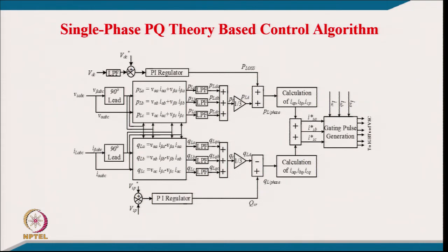All these 6 quantities consist of ripple and a DC component. The DC component corresponds to the fundamental active power and reactive power, which we get using the low pass filter. These can be different values, because you might have an unbalanced load. Similarly for quadrature, the reactive power DC component can also be different, as you might have load unbalancing across all 3 phases. So, summing all 3 and then dividing by 3, we try to balance as a per phase value.